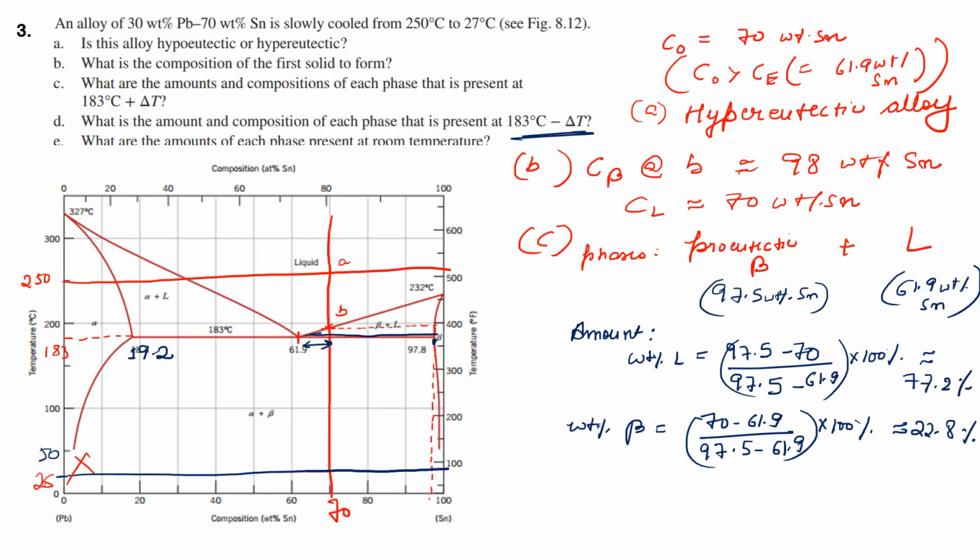So if we just take an approximation and extrapolate this solvus below this 50 degree limit that we have right now, if we just go this way, it approximately comes out to be about 2 weight percent tin. And this approximately goes, if you extrapolate it, it touches 100 because it's already very close to 100 here.